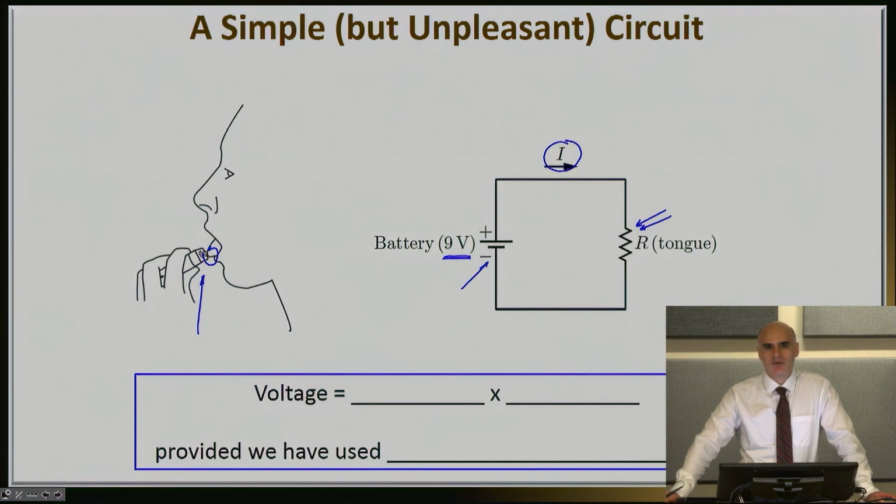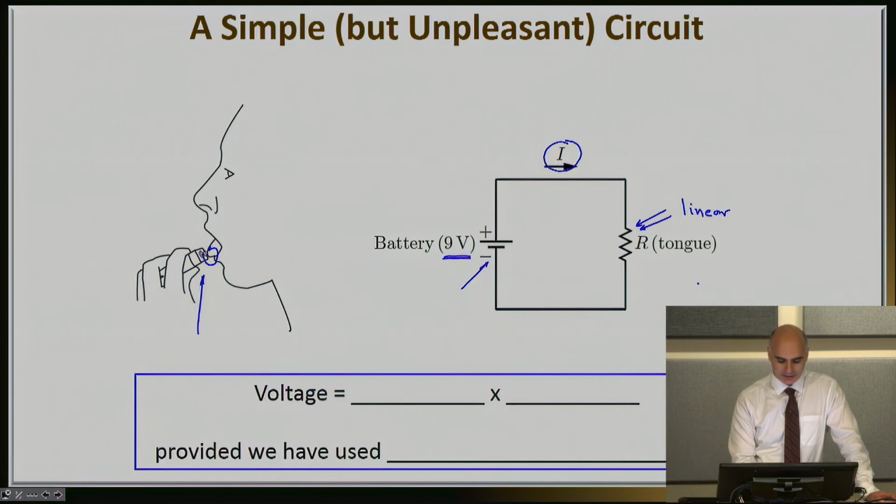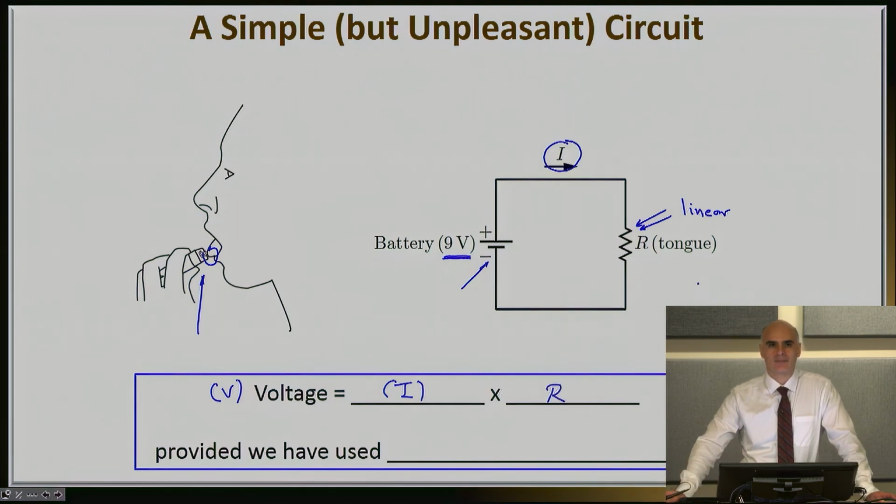If you were to double the amount of voltage, then you would end up with precisely double the amount of current. In other words, this is a linear element. It's a linear resistor, and every ideal resistor is practically a linear device. Now, this rate of proportionality that links the voltage V to the current I is called resistance, and it has the symbol R.